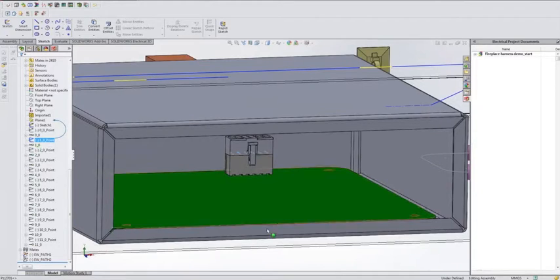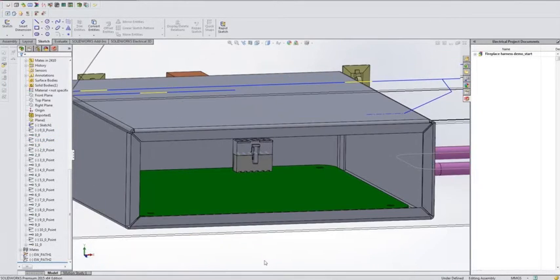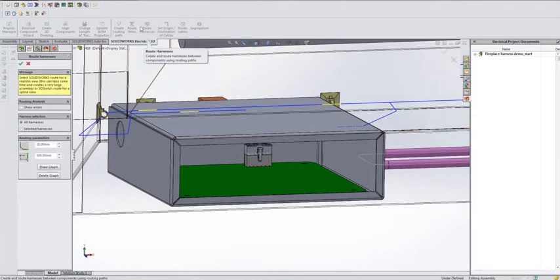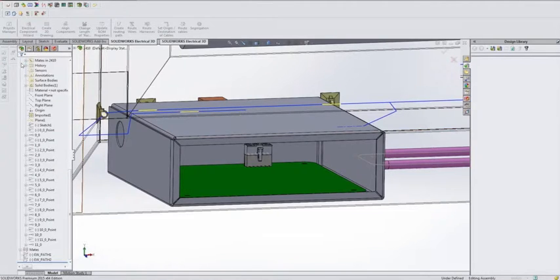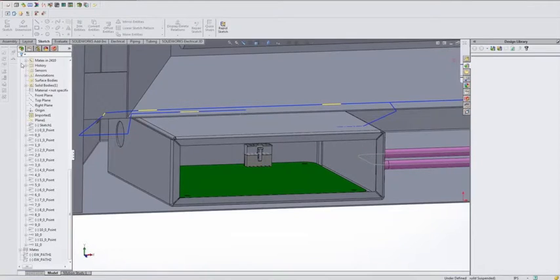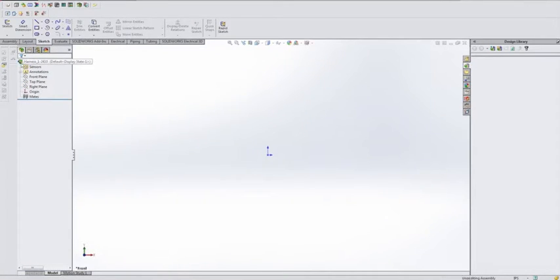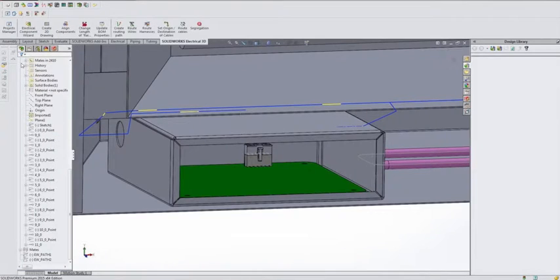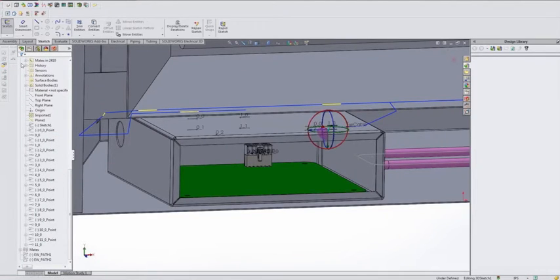So once we go ahead and do that, we'll go ahead and route this up. So it's really simple. We'll go to SOLIDWORKS Electrical 3D, and then route harnesses. I'll select all my harnesses, press OK. And what it's doing in the background, once again, it's referring to that sketch and saying, okay, route along this path. And what it's connecting up is it's looking at the SOLIDWORKS Electrical 2D side. It's using that schematic, and it's going to go ahead and drive pretty much our routes, how things are connected.